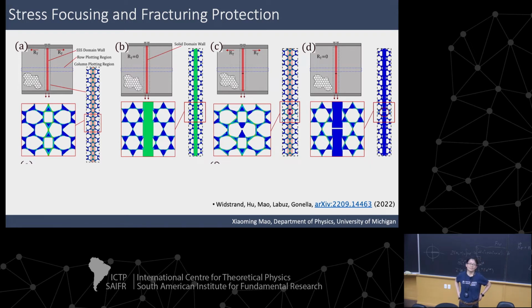When I think of fiber reinforcement, I think of putting in a material which has an ability to bear load. Here, it seems that the ability to bear load is the same. It's just focused there. Is that wrong? Yeah, I think you can think of it in this way. You can intentionally use more material at these domain walls. And then you can make the whole thing lightweight by making the bulk much weaker, because now the bulk doesn't do anything. Okay, right. Thank you.